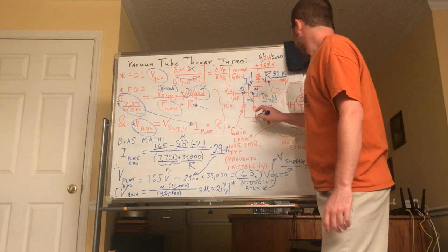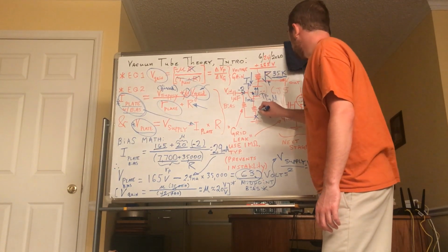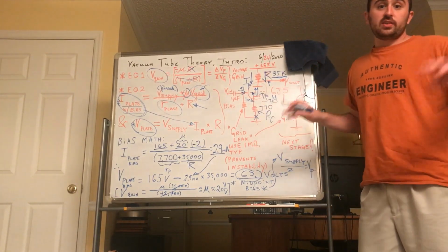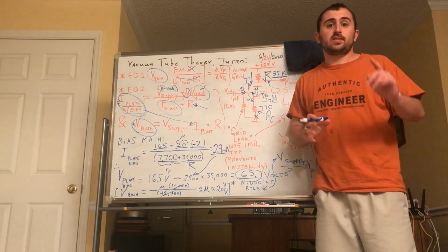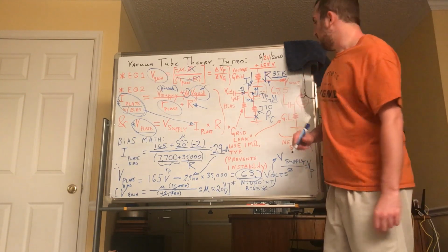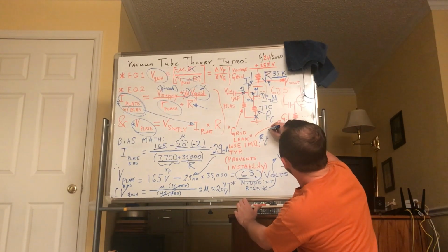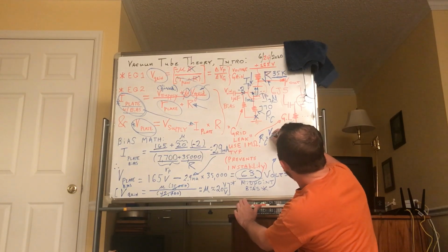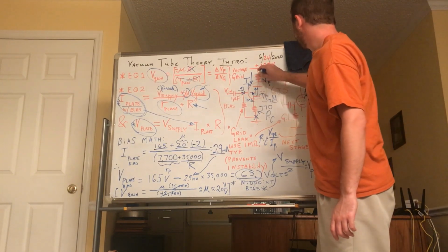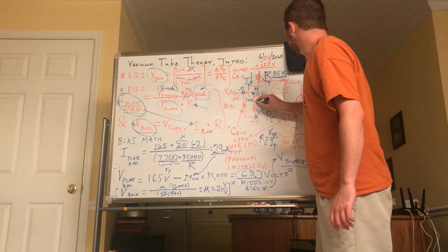So we do the following. We put 1 meg resistor between there and ground. You might wonder about what this resistance does. Let's call it RC. That's our self-bias resistance. In the previous example, I used a battery to bias this thing. In this example, we're not going to use a battery to bias it. We're going to actually instead make it bias itself. And how this is done is RC is set to the value of V grid divided by I plate via Ohm's law. So what we have is, conventionally, we have 3 milliamps here, roughly, and we need 2 volts.